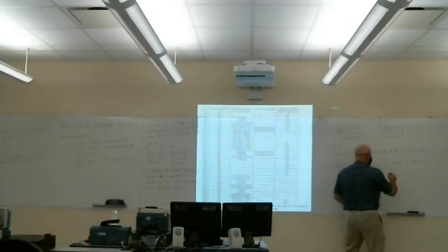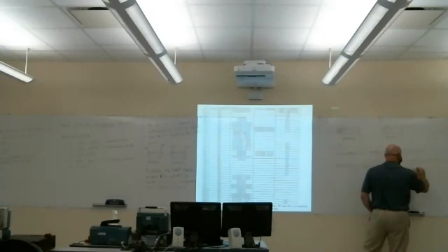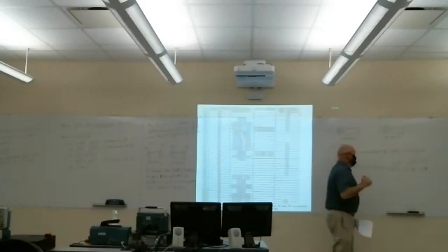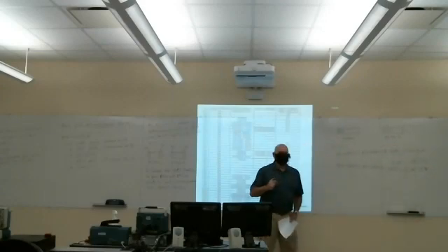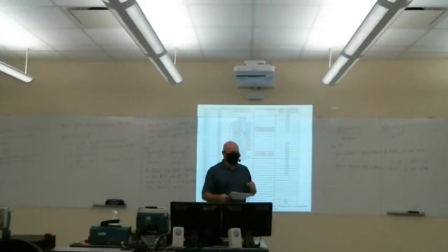So we want to OR with 0xC0. That will set B6 and B7. More importantly, it doesn't change any of the other bits. We read the current value, OR, and then write that value back.